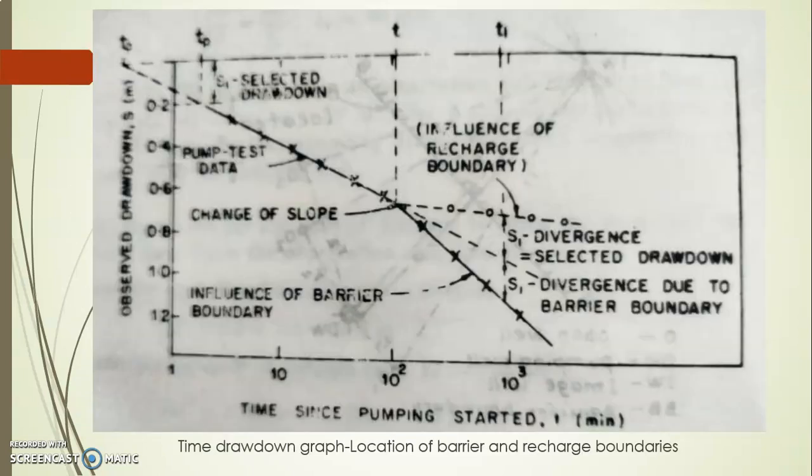The image shows here the time-drawdown graph by the location of barrier and recharge boundary. The pump test data will be noted down with respect to observation drawdown s and then time, and there will be a deviation in the curve obtained by the influence of the barrier boundary.